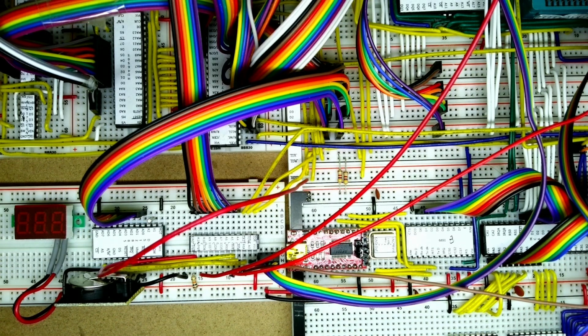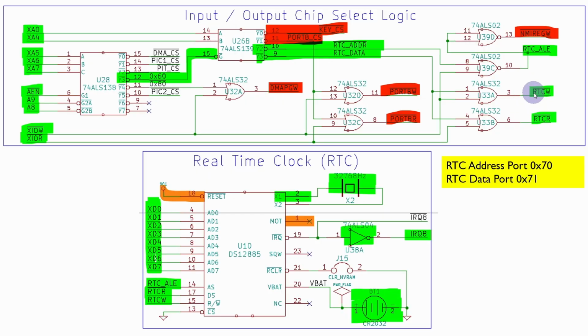And just to show you where I'd gone wrong, you can see here that the RTC write and RTC read are active low, but in fact the RTC address latch enable, address strobe, is actually positive. In fact, when I went through and checked out this gate here, these are OR gates, this is an OR gate. So in fact I had the signal here inverted. So when you get two zeros here, so IO write and the address select, then this should go to 1 and it should be 0 the rest of the time. So that was a small change I had to make.